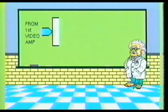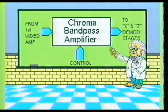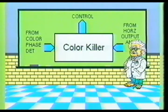We will now pause for a short review of the material just discussed. The primary function of the chroma bandpass amplifier is to separate the chrominance information from the composite video signal. It also amplifies the color information. The color killer stage is used to control the operation of the chroma bandpass amplifier section. The color killer has the ability to turn the bandpass amplifier on or off.